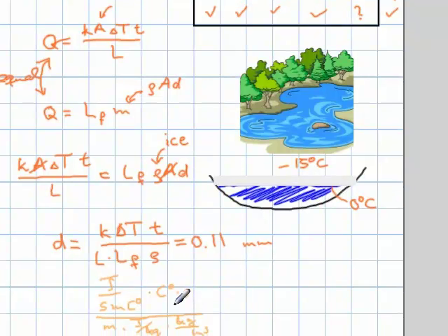And then when we look at all the units, well, the Celsius degrees here divide, the seconds divide here. Let's see, kilograms, here's a kilogram that divides by this kilogram, and there's a joule divided by that joule. And then there is divide by meter, divide by another meter, so that's per square meter, and then divide by the reciprocal of cubic meter, so it's going to be cubic meters, this one here, divided by square meters, which of course is meters.